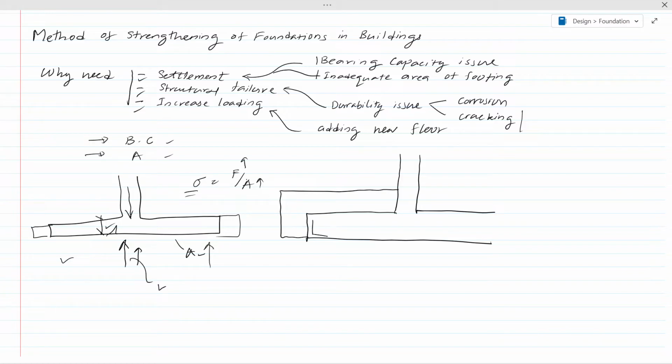You might have a footing reinforcement like this. Now this is the part we are going to add. Now we have to bond these two sections. You can have the dowels there, so this will take up the shear action.